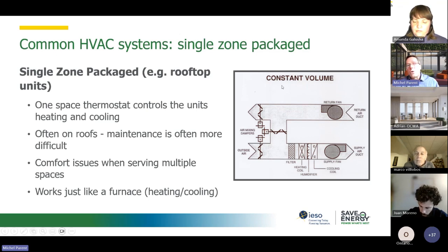And then when you do your walkthrough, you will open the compartment to the damper compartment, because you want to have a look at those dampers. You need to identify how much the outside air dampers are open when there's a heating or a cooling coil, which we typically call the minimum outside air. And that will give you a position of the damper, not the flow.